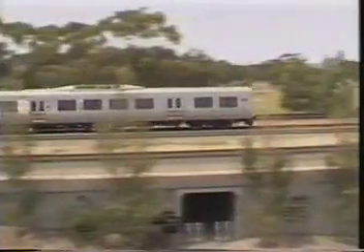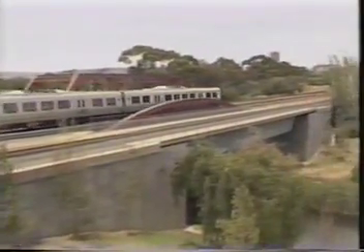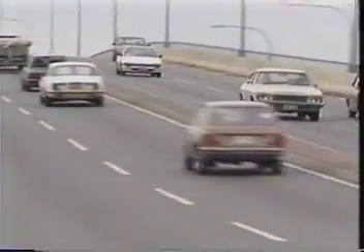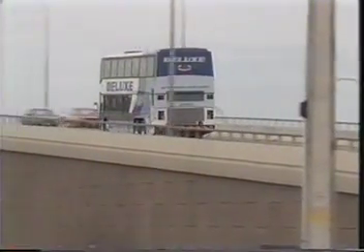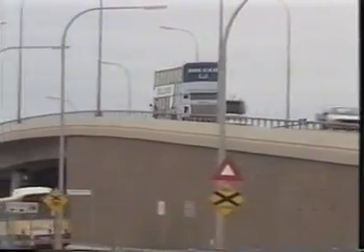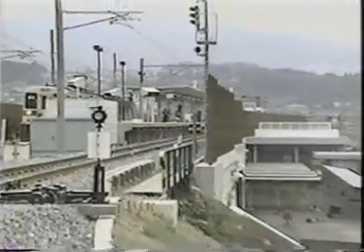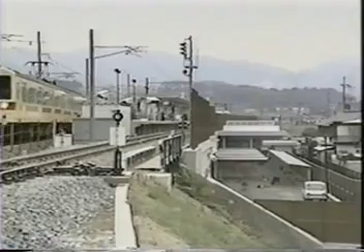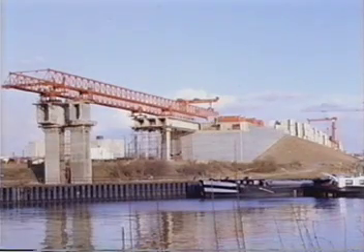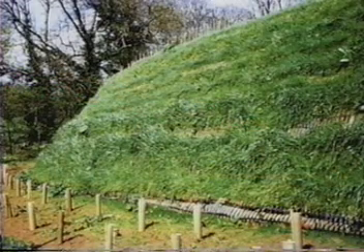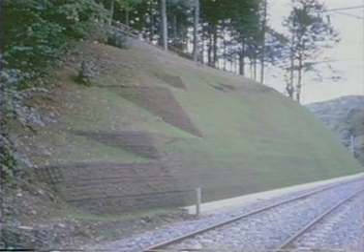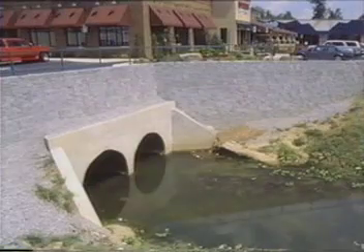Design lives may range from a few months for a temporary facility to 120 years for a permanent structure such as a bridge abutment. Design life is largely controlled by the ability of the soil reinforcement to provide the requisite stabilizing forces over the required service life. With appropriate design, reinforced fill is highly resistant to seismic loading. The agent of degradation for steel is mainly electrochemical corrosion, while for polymeric reinforcement, it is primarily creep. The load that a reinforcement could sustain will therefore decrease with increasing time. This fact will be allowed for in design.